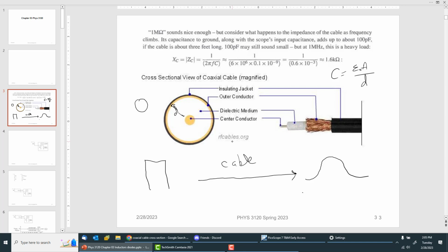If you look at a cell phone tower, there are these things that look like cables running up the side, right? They're actually hollow metal tubes. Because at 2.4 gigahertz, coax cable is good to about 300 megahertz. So above that, you can't propagate the signal efficiently. So you end up using something that doesn't have any center conductor.